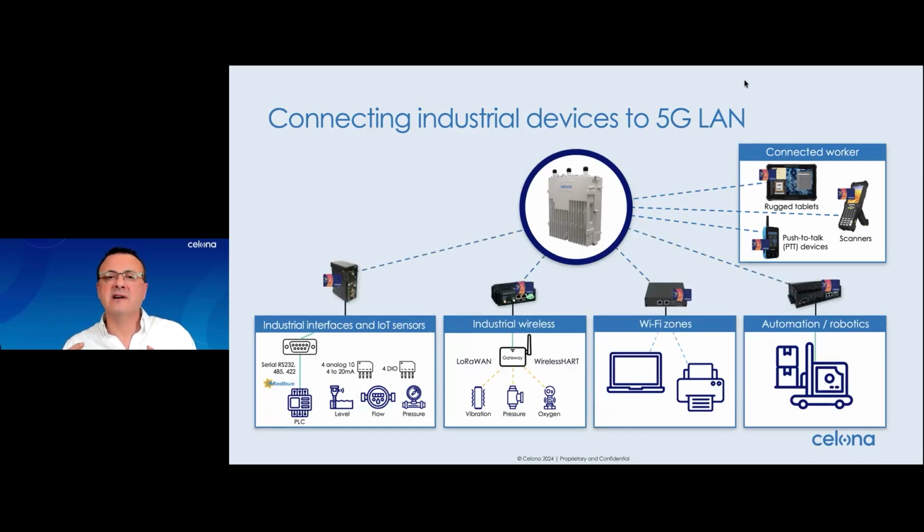We use industrial-grade gateways to act as protocol and access bridges between the legacy and/or non-cellular devices to private 5G. These gateways connect upstream traffic into private 5G and downstream using whatever interface devices support. So you can have Wi-Fi or Ethernet or serial or fieldbus or even low-power wireless protocols. Depending on the environment and use case, we see different gateway form factors, everything from mobile routers mounted on AGVs to fixed industrial-grade factory floor gateways.